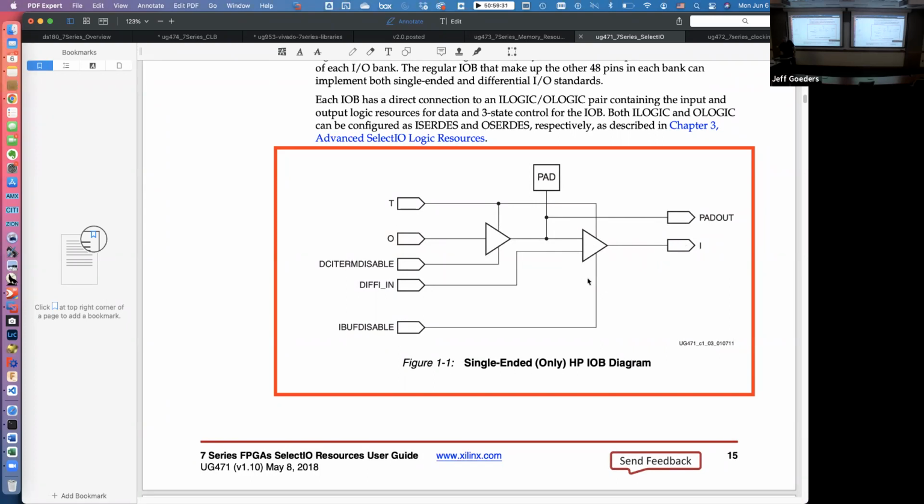But what are these other signals? We have 3 other signals coming into the buffer. For a simple input, they aren't used, but can you see that you can disable that buffer with this signal? Okay, and the tools will have to tie that low if you don't want to disable it, right? But if your design needs it, there it is.